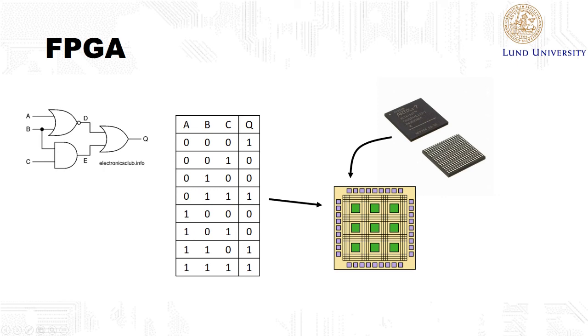It contains an AD converter, PCI Express interface, gigabit transceivers, PLL for scaling the clock frequency, special hardware for digital signal processing, 13 megabit memory, and has around 500 input-output pins, which can be connected to other parts of a system. This FPGA contains around 15,000 configurable logic blocks, or CLB, which is where you implement your logic functions. Each configurable logic block contains 8 6-input lookup tables and 8 flip-flops. Other vendors might call these blocks different things.